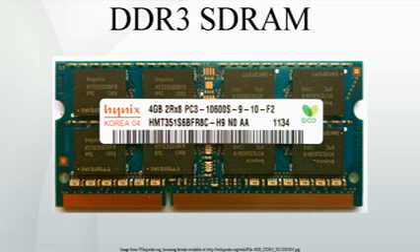Another benefit is its prefetch buffer, which is 8 burst deep. In contrast, the prefetch buffer of DDR2 is 4 burst deep, and the prefetch buffer of DDR is 2 burst deep. This advantage is an enabling technology in DDR3's transfer speed. DDR3 modules can transfer data at a rate of 800 to 2133 MT/s using both rising and falling edges of a 400 to 1066 MHz I/O clock.